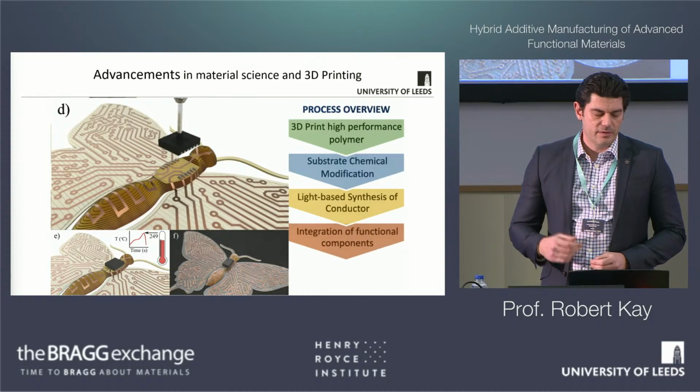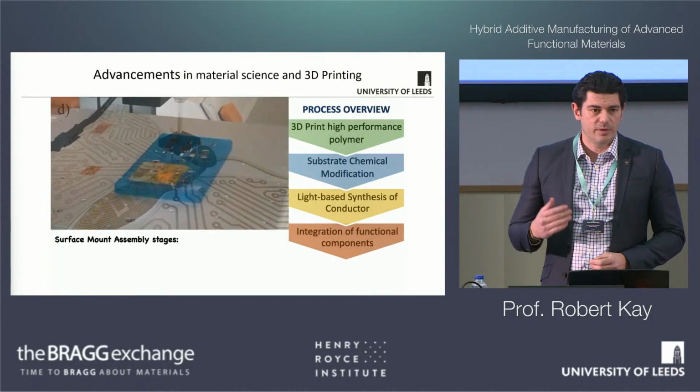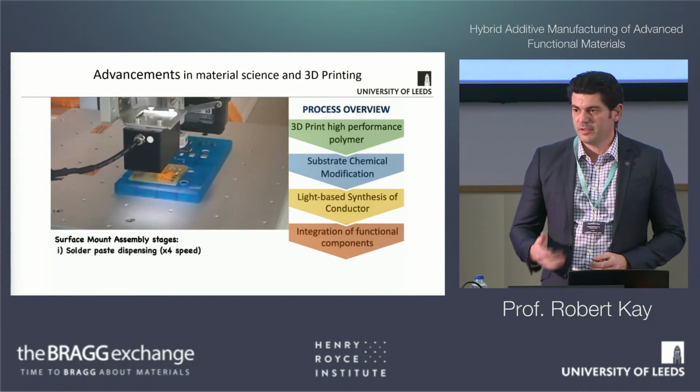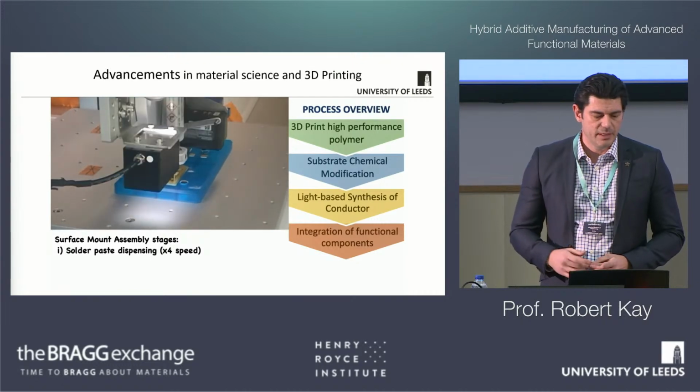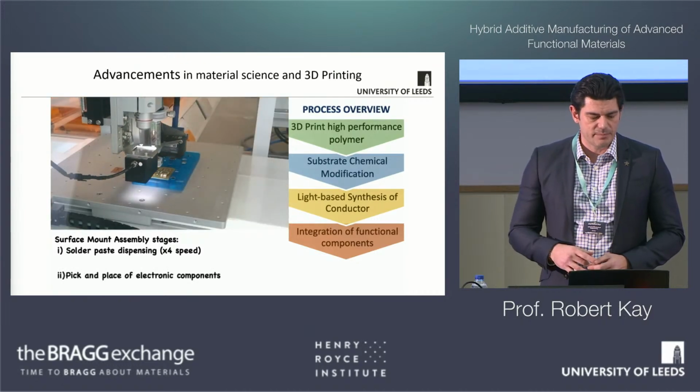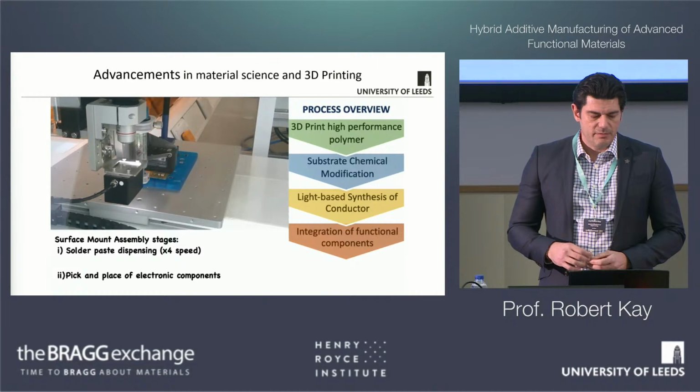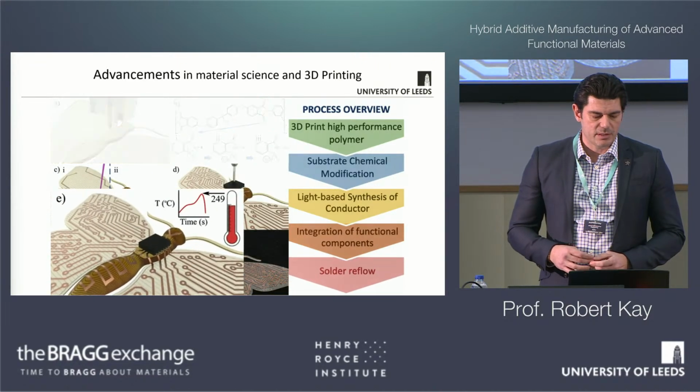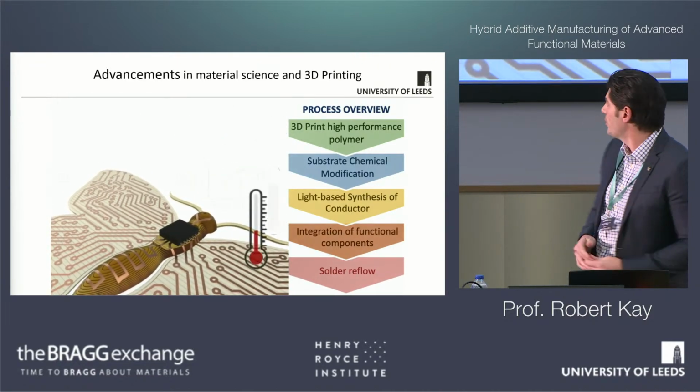We then dispense solder paste, because again, we want this to be a digital process, so we don't want to use any templates like stencil printing, and then we'd pick and place the components. And then finally, we reflow the parts using a standard solder reflow process.